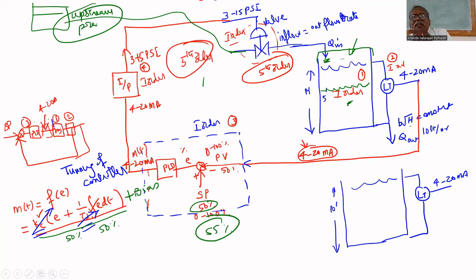No need to know why level is decreasing. It won't ask. If level decreases, it will open the valve more. Yesterday, I opened 50%, this much flow rate. So for this error, I will open this much only. It won't say that. If level decreases, automatically it will open more. That is the function of a PID controller. So if any disturbance enters the process, there will be a change in valve opening. That is done by this controller. This way it will be controlled.